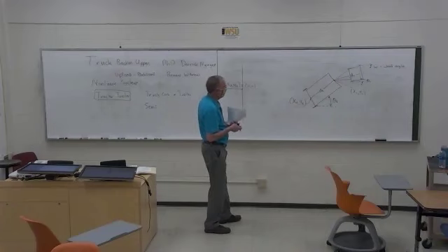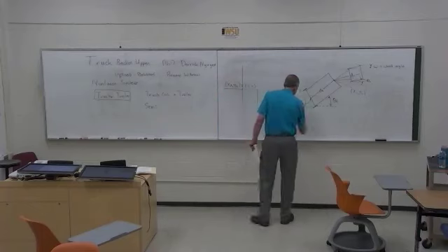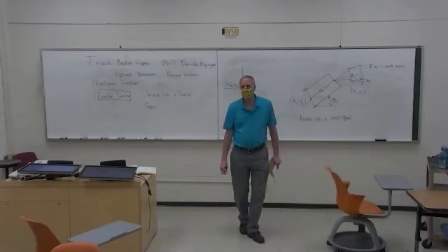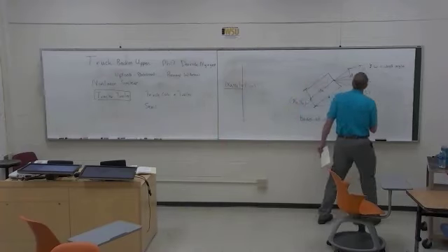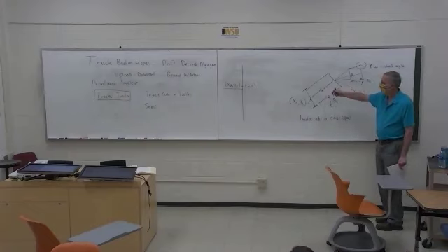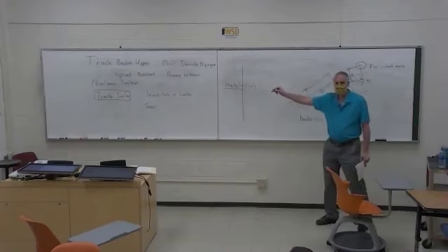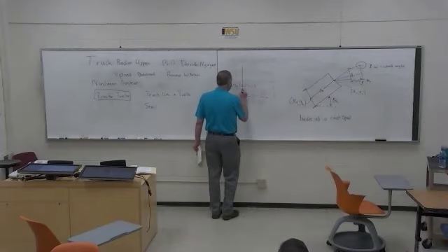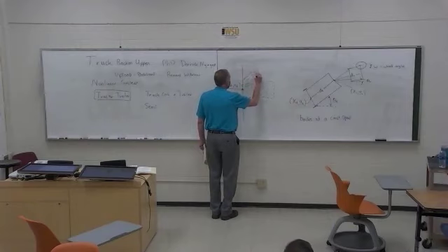And so this problem is set up so that it backs at a constant speed. So we're not trying to control the speed, it's just kind of an idle backing up. And the neural net is the artificial driver, and it's going to control the wheel angles as a function of time, so that no matter where the truck and trailer start out, it eventually backs its way up to the dock. And so the goal is to get the trailer backed up with that endpoint right at the dock, and theta of the trailer equals 0.